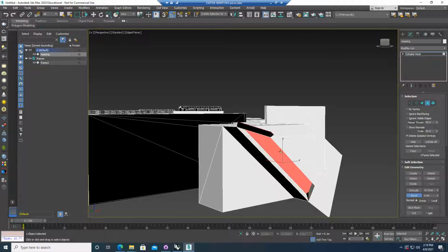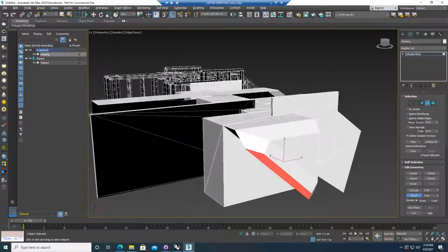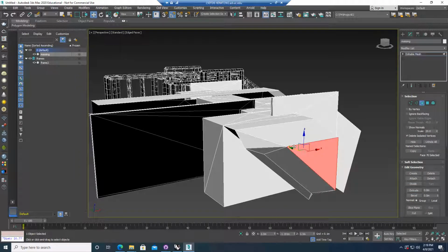You can do this to any face you like, and then move. So now you have this smaller face. Okay, so this is the freeform modeling, a very easy approach. You can definitely do a lot of this kind of operation on top of your model to make manipulations. And any time if you pick the original face, you can always press W to move. So if you want to change the shape or the proportion, this is really easy to do.